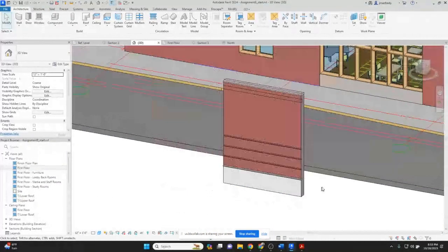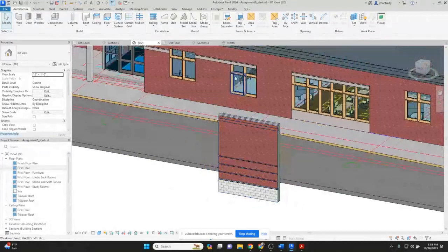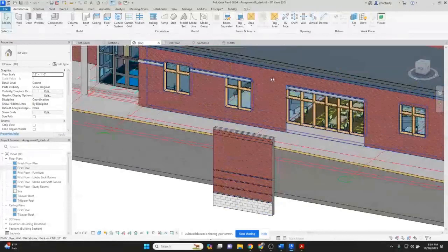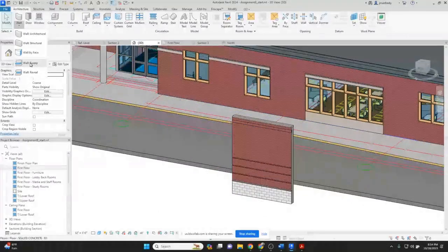We did not do it this way, because if I built the wall this way with those details embedded in it, the entire wall would have that detail, and I can't remove it from one place to another. Then I'd wind up having to make this wall a different wall with and without that lintel. That doesn't make a whole lot of sense. But these drawings are using the same profiles, and the profiles can be either what they call sweeps or reveals. Reveals cut a hole in the wall. Sweeps add something 3D to the wall.